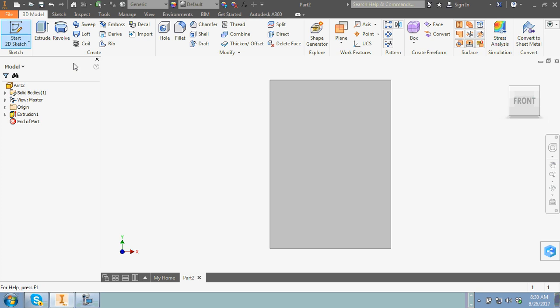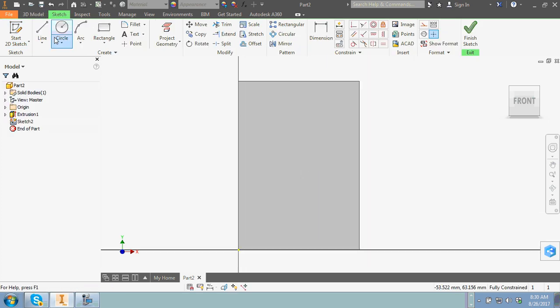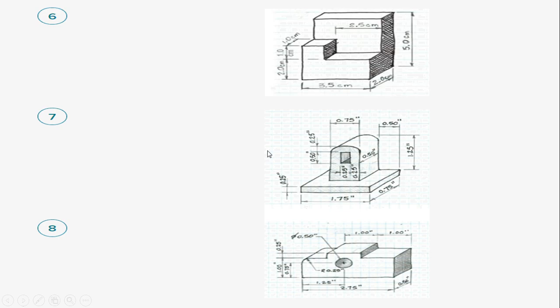We're going to click on our pencil, and we're going to click on our front view. Drag my front view down. I'm going to click on the line command. The line is in the top right-hand corner. I'm going to click and drag over until I snap over to here. Straight down, I'm going to put in 2 centimeters. I can just hit enter after I do that. And to the right, let's see how far I'm going to drag over to the right. We have 3.5 here and 2.5 up here. So this distance right here will be 1. 2.5 from 3.5 is 1.